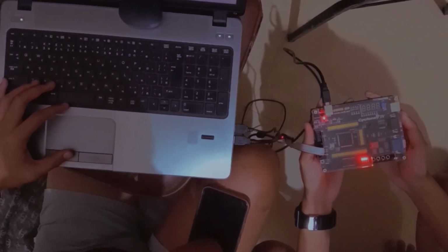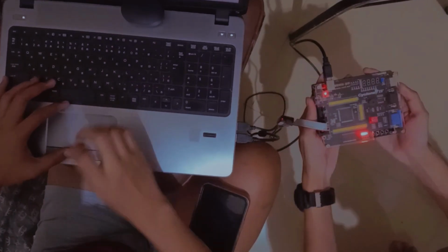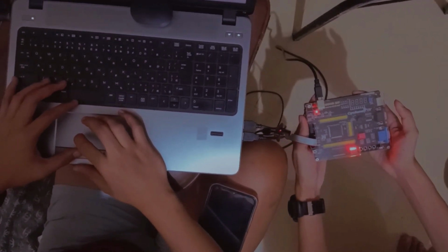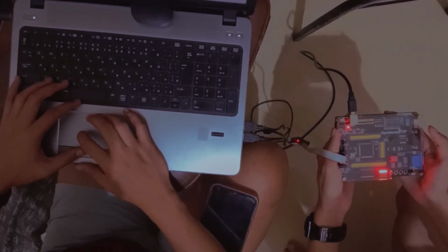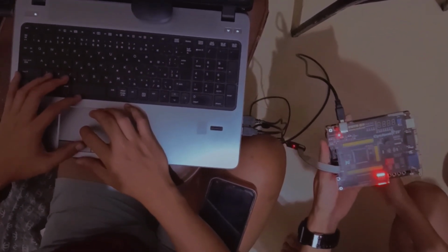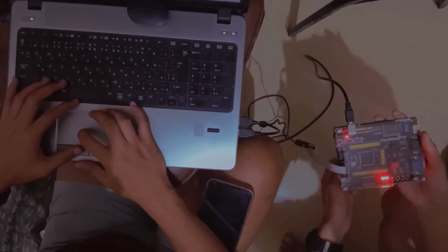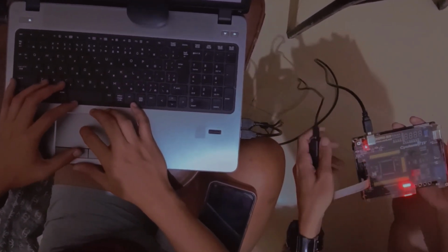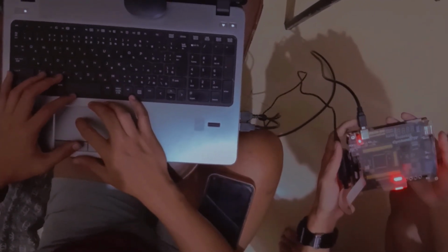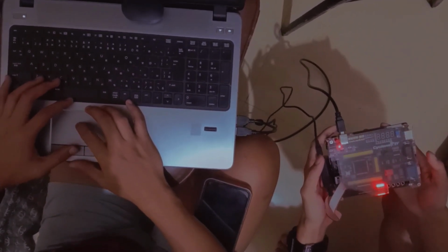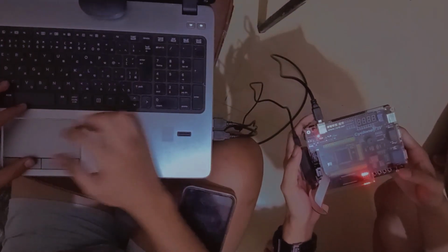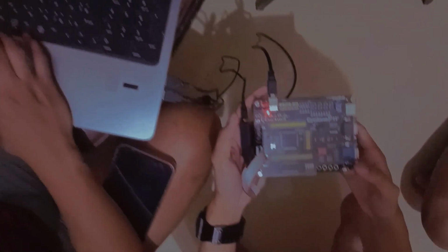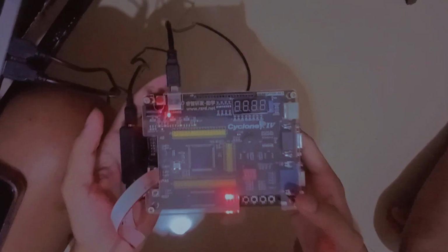The clock input serves as the clock signal for the circuit. On each rising edge of the clock, the circuit updates its internal state and outputs. The circuit consists of registers that store the current state, digit selection, display data, and a counter. These registers are implemented using flip-flops within the FPGA. The state transition logic determines how the circuit progresses from one state to another. Each state transition updates the state register.